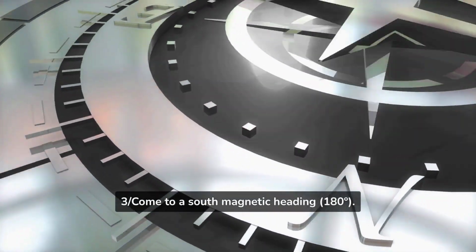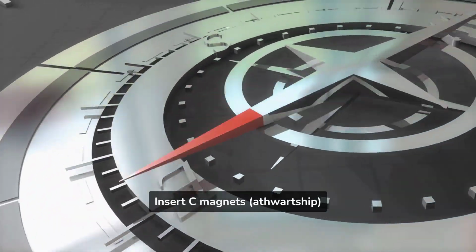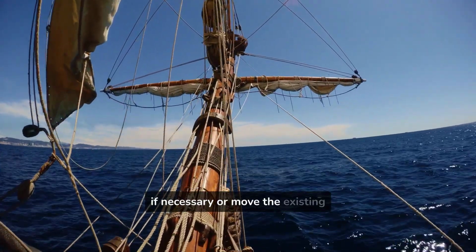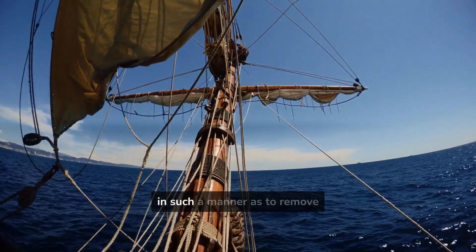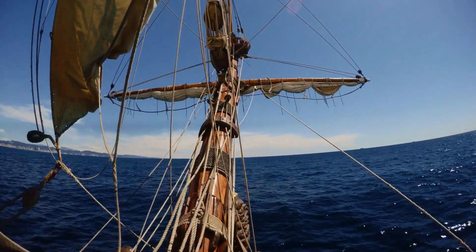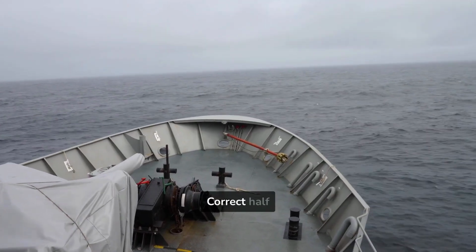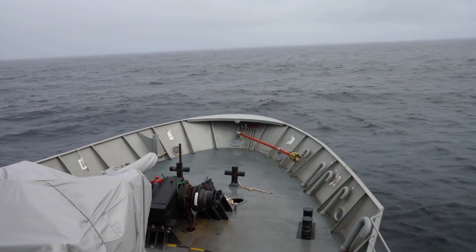3/ Come to a south magnetic heading, 180 degrees. Insert C magnets, athwartship, if necessary, or move the existing C magnets in such a manner as to remove all deviation. 4/ Come to a west magnetic heading, 270 degrees.